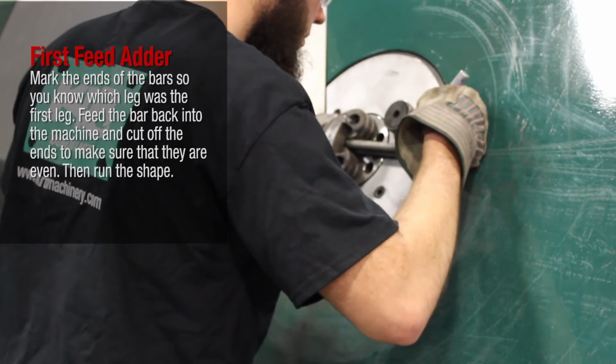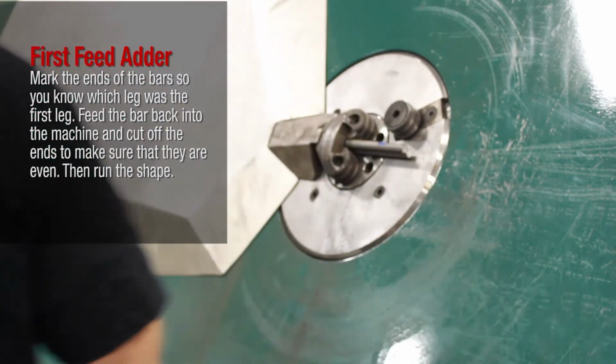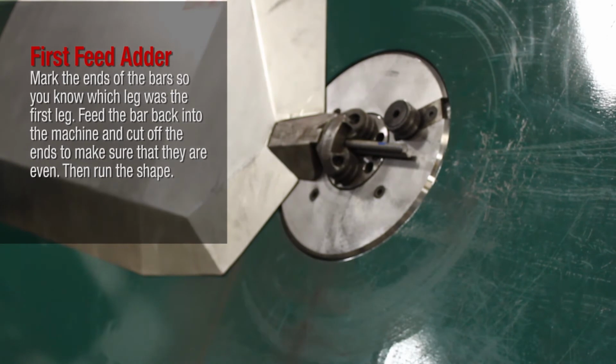Mark the ends of the bars so you know which leg was the first leg. Feed the bar back into the machine and cut off the ends to make sure that they are even. Then run the shape.